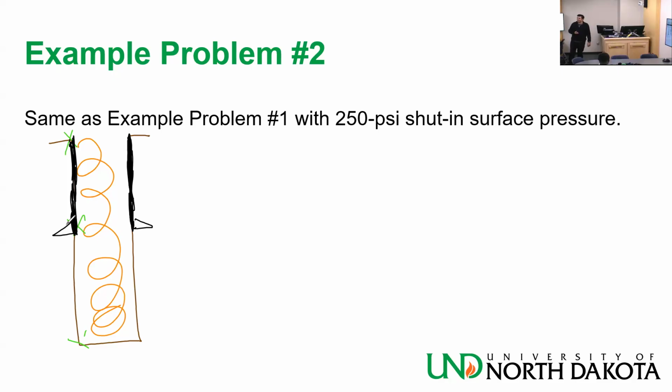It's based on the shoe. Yeah. That means now I'm protecting everything up to that point. That means now I'm really worried, when I'm drilling, about what happens here. Because if I fracture here, that's the easiest place to fracture, right? That's the most vulnerable point, the casing shoe depth.